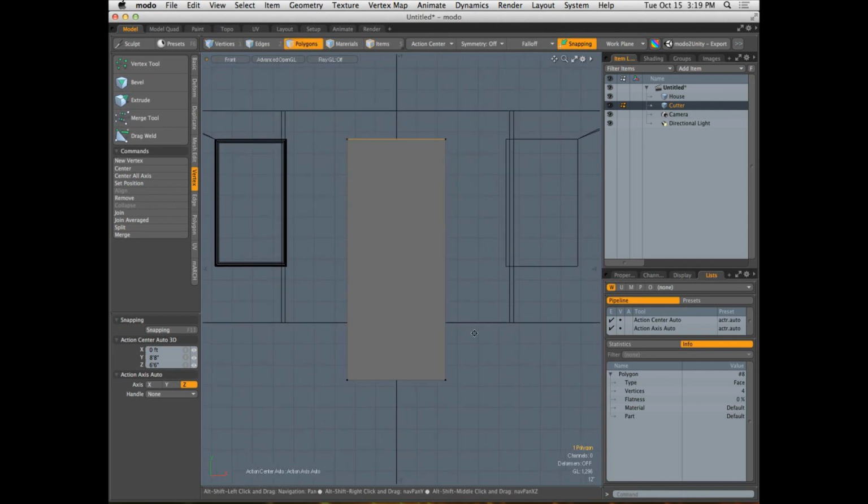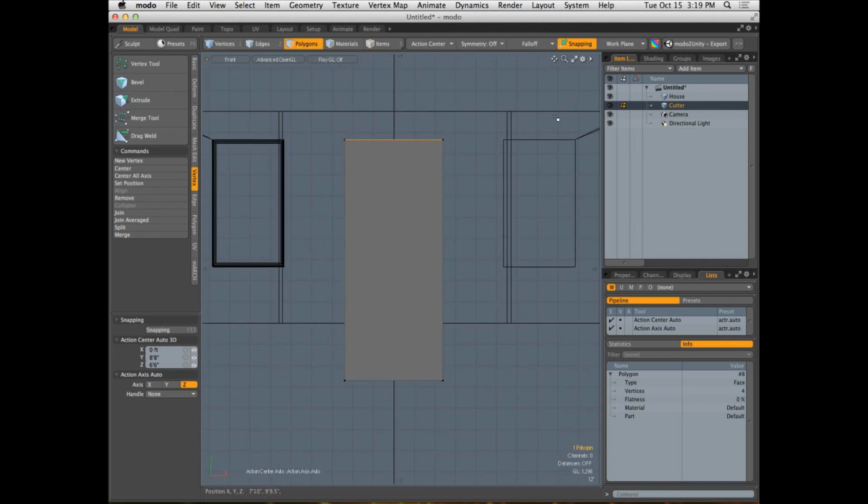If we look at our scene from the front, when we do the boolean, the cutter as well. Uh-huh. With the door, even though we're going to have a solid material there, I'm going to have an opening for my door. Often, if you look at the models that we make for architectural visualizations, the door is going to be its own separate mesh item or separate discontiguous polygonal piece. That way we can open and close it. We can pose the door where we want it to go. It's a good idea to have some of those basic movable parts on a house be separated out from the mesh so that we can control it.